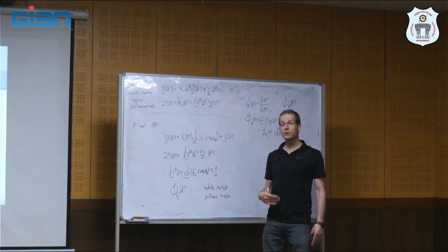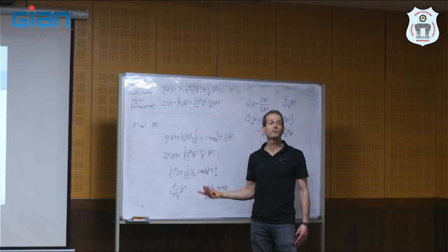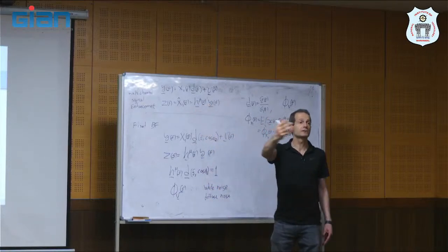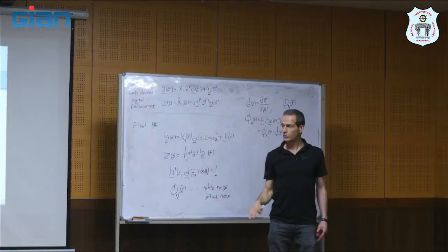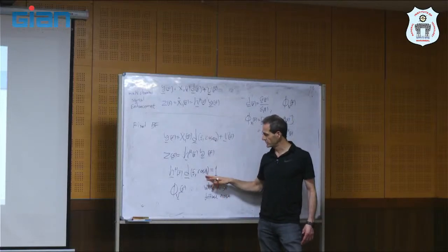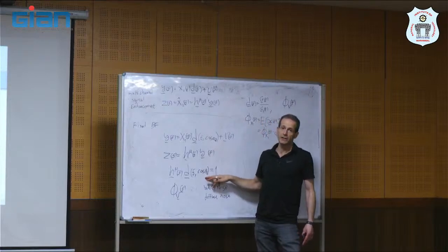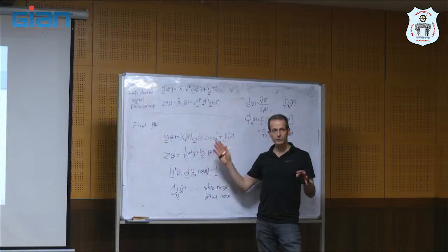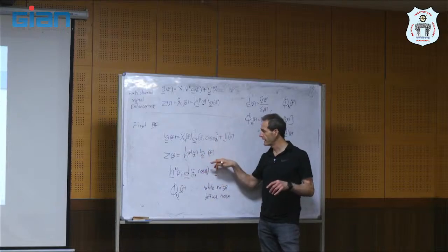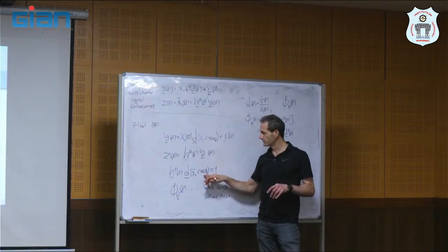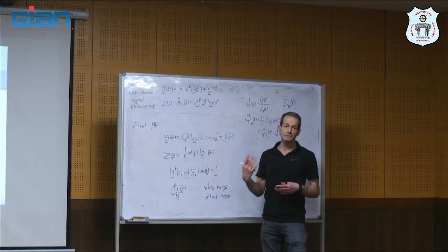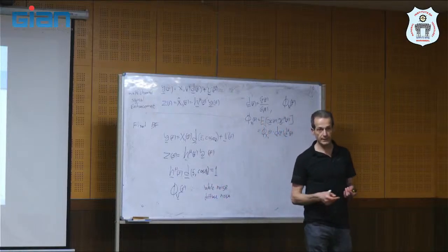Or we want to know what will be the effect of noise that propagates from a certain direction. Of course, if the noise source also comes from this direction, it will be undistorted, and will be at the output of the beamformer. But if noise comes from another direction, it will be suppressed, okay?